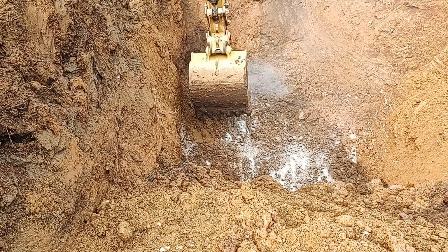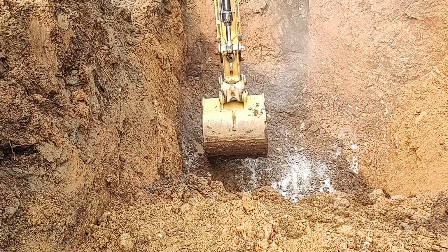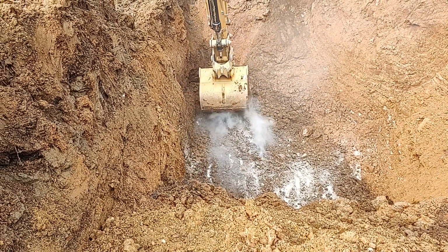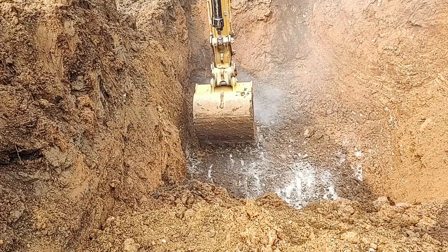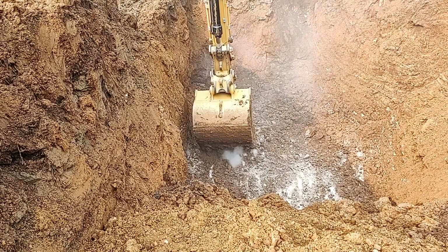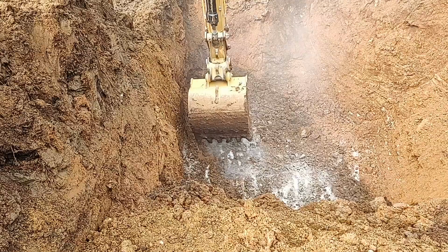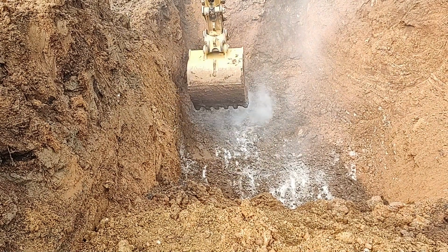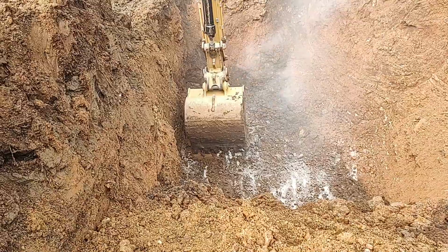Here we're using a large excavator to dig a core trench to make a foundation for a groundwater dam on limestone rock. The limestone is in layers with many cracks between the layers. The operator is not able to peel up and remove these thin layers of rock. The teeth on the excavator bucket slide across the surface and they don't dig in for bringing up the rock.